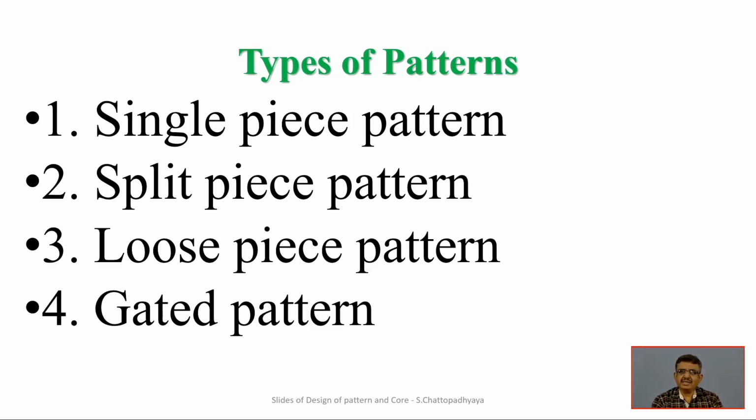And the splitting strategy all depends upon the complexities of the job, and people require a lot of expertise, the gray hair people are associated with, to decide about what kind of split patterns will be there in order to ensure the easy and defect-free withdrawal of the pattern from the mold. Then loose piece pattern. Sometimes it is so complex that we have to use some loose pieces here and there in order to create all those cavities. So loose piece patterns will be very suitable for those kind of cases.